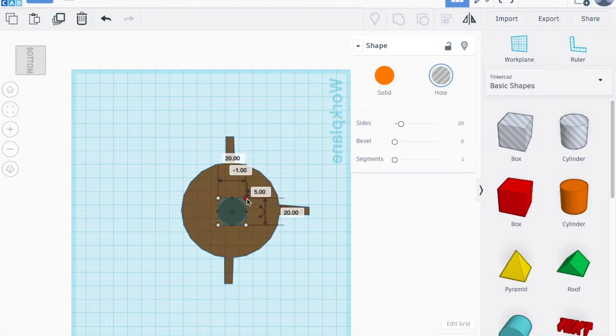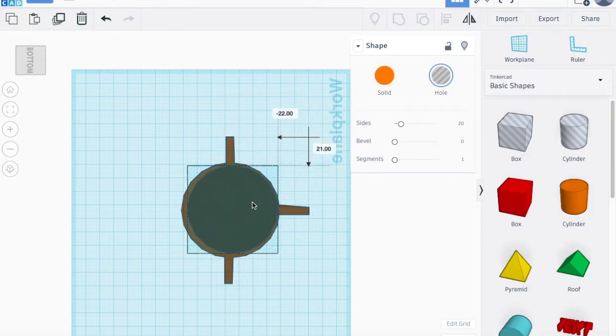So I'm going to make this 60 by 60, just once I've got it into the right place. Again, you can click on the wee white square in the corner. It says it's 20 by 20, but I'm going to make it 60 by 60. That means it will hollow out the whole shape, but leave me with a small border on the outside. And I'll just use the arrows on my keyboard to make sure it's centred.